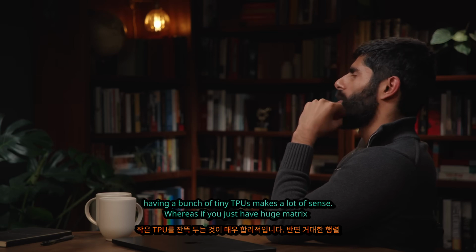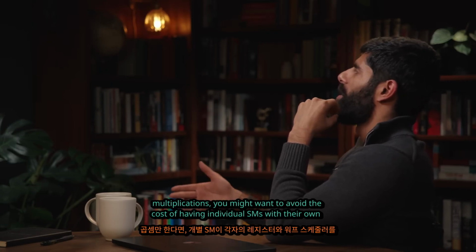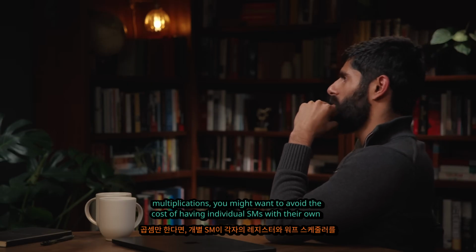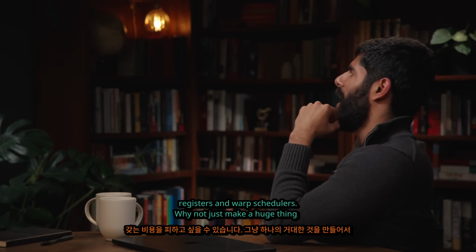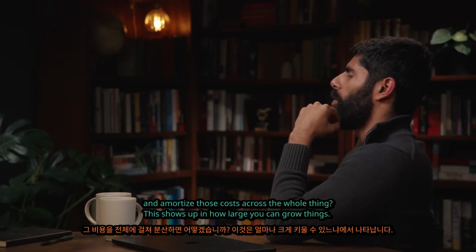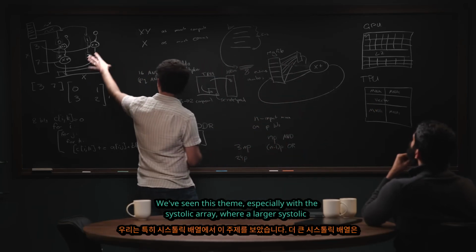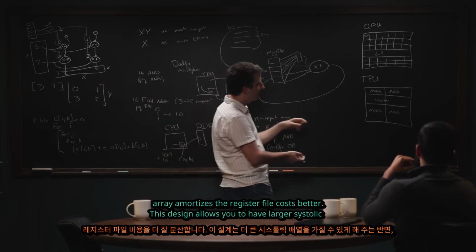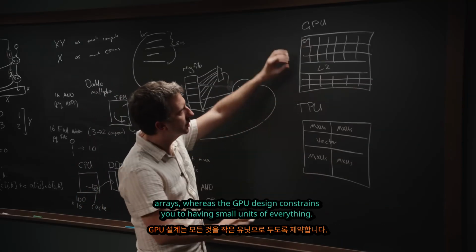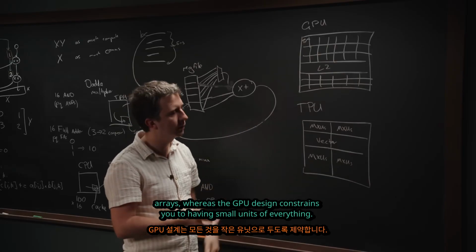Whereas if you just have huge matrix multiplications, you ask: why don't we avoid the cost of having individual SMs with their own registers and warp schedulers? Why don't we just make a huge thing and amortize those costs across the whole thing? I think this shows up in how large you can grow things. We've seen this theme, especially with the systolic array, where a larger systolic array amortizes the register file costs better. This sort of design allows you to have larger systolic arrays, whereas the GPU design constrains you to small units of everything.